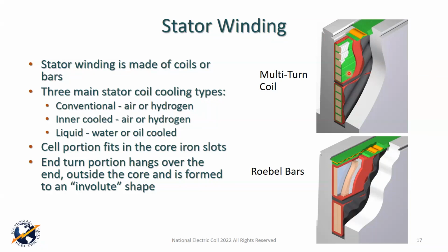When you get the coil in, it's important to keep the coil tight in the slot for mechanical reasons and also a couple of electrical reasons that have developed in the last 20 or 30 years. One of the ways that's pretty common to do that is to use side ripple filler. You see the black that's here and it's got a wave in it. I'll show you some pictures of this in a minute. That's driven in there with the idea that that wave is going to be flattened out, not completely, but maybe to 85 or 90% at the max. That gives constant tension on that coil and acts like a lock washer to keep the coil tight in the slot.